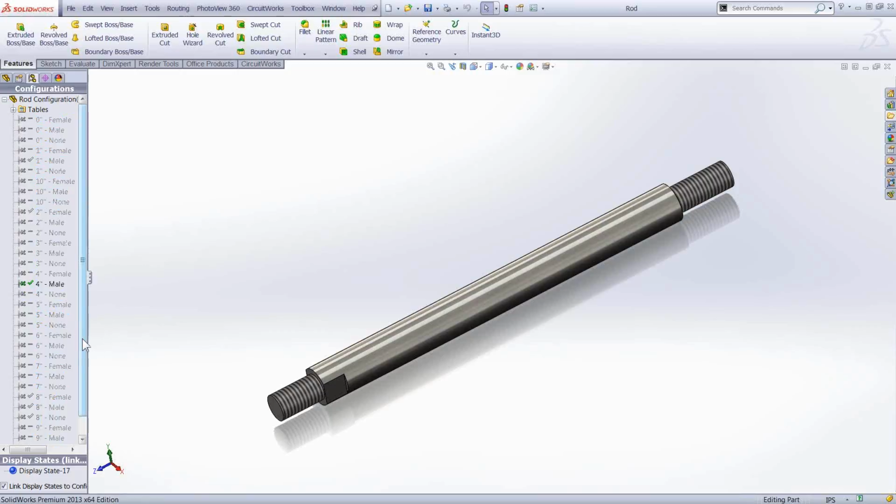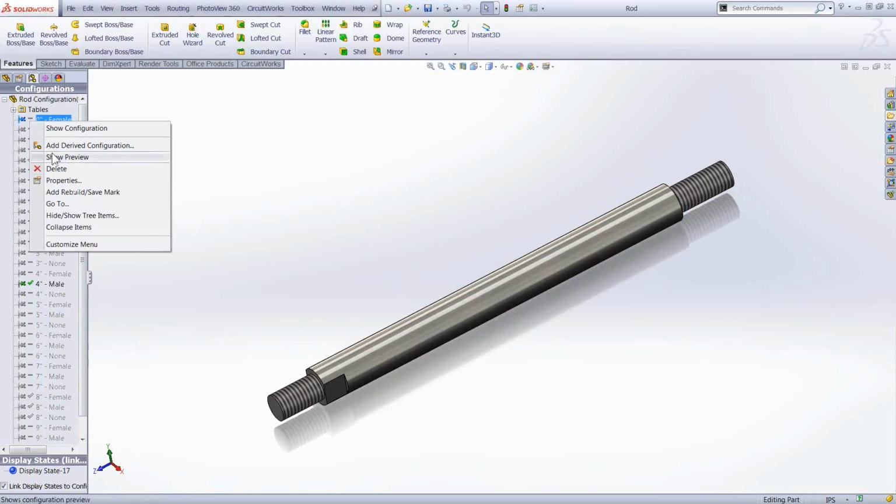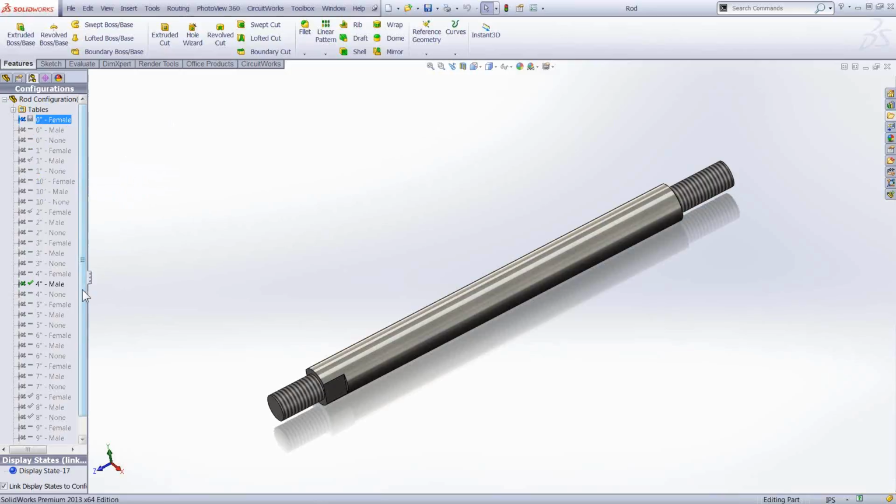So if you have a part that you want to get loaded into cache all the time, the best way to do this is just to right click and go ahead and set it up so that it adds the rebuild and it gets cached with it. This is a great way to save space on your files if you're having to move your files around some.